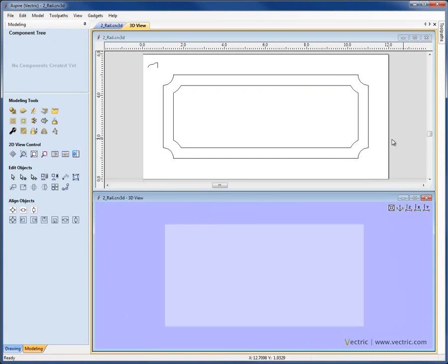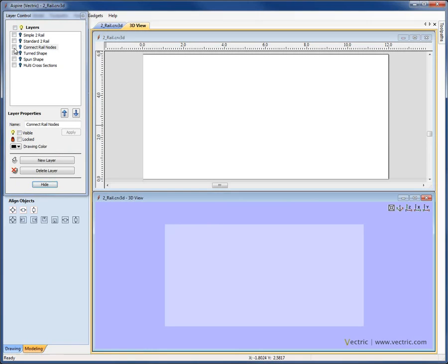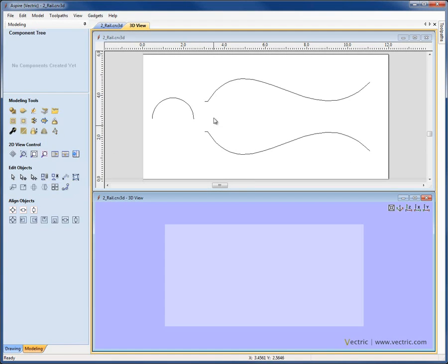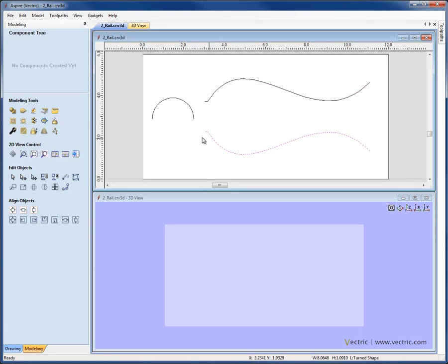And I'd like to show you a couple of examples that don't use any new options within the two-rail sweep, but are particular types of shapes that you may want to build, so it's useful to see how you would go about building this type of shape using the two-rail sweep function. I'm going to hit Ctrl L to bring up the layer manager, choose the layer with the vectors, and here you can see I've created two rails, and these effectively are the sides of a vase type shape. This could also be something like a column, a wine glass, a spindle, or anything that effectively is a shape that you could turn on a lathe.